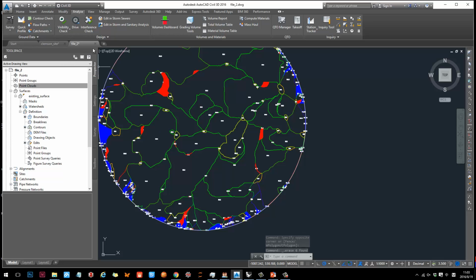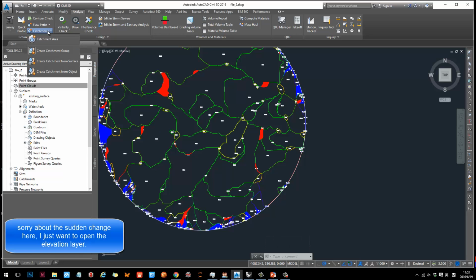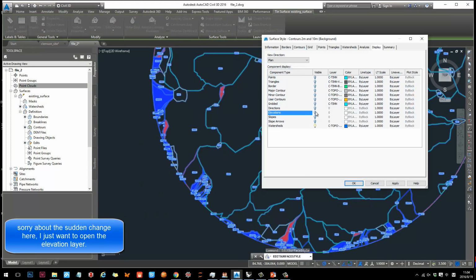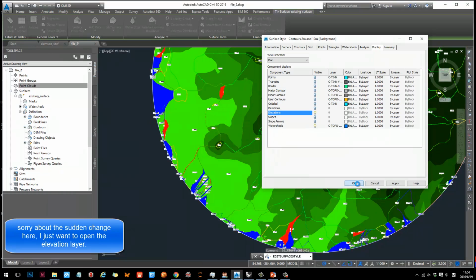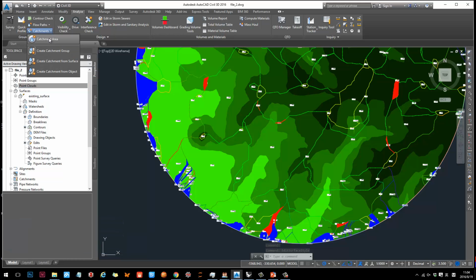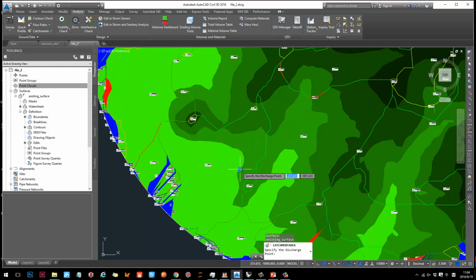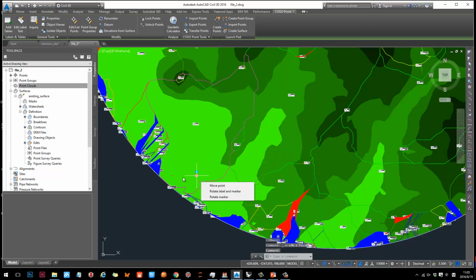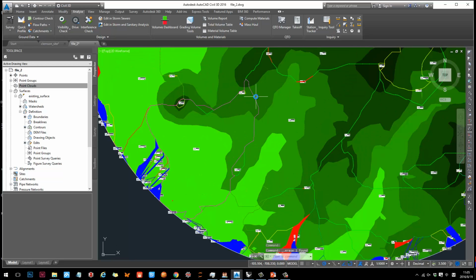So this is watershed, and the other thing you need to know is catchment. Catchment is a little bit different. Elevation again. If you go to catchment and catchment area, click OK, and for example I select somewhere here, you'll see it defines an area for you.